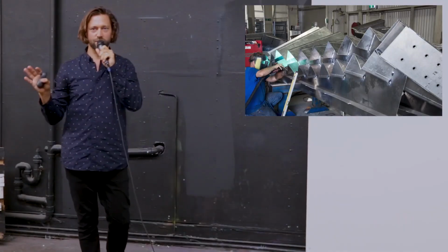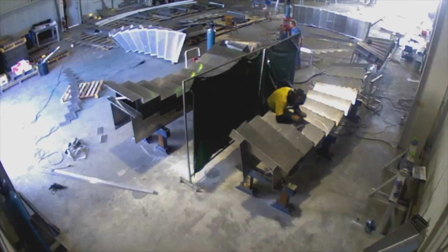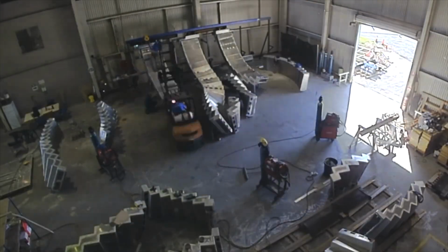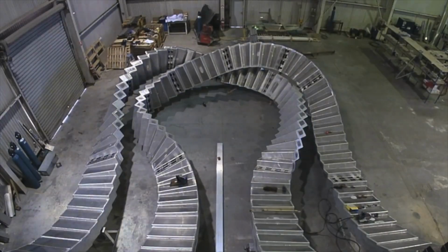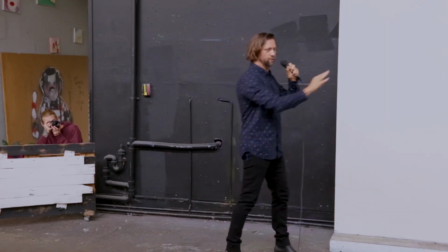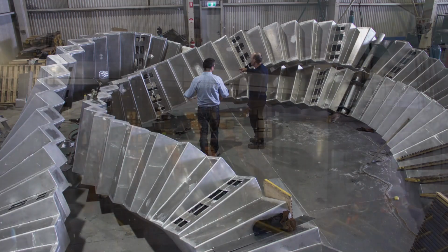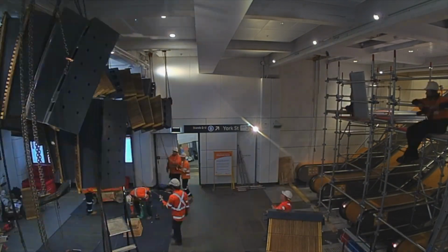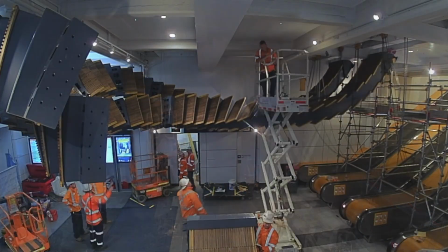And in fabrication terms, doubly curved surfaces are pretty complicated and expensive if you're trying to do it out of sheet material. And we spent so long trying to work it out. Like, maybe we have to facet it, or we could radius it off. Maybe we could 3D print it. Maybe we could get a 6-axis robot. And the fabricator's like, no, you just push it. And so they just pushed it. And what was good was that they just pushed all the metal into those positions. These are all perfectly radiused, but the outer skin, they just basically work like a light gauge timber sheet.